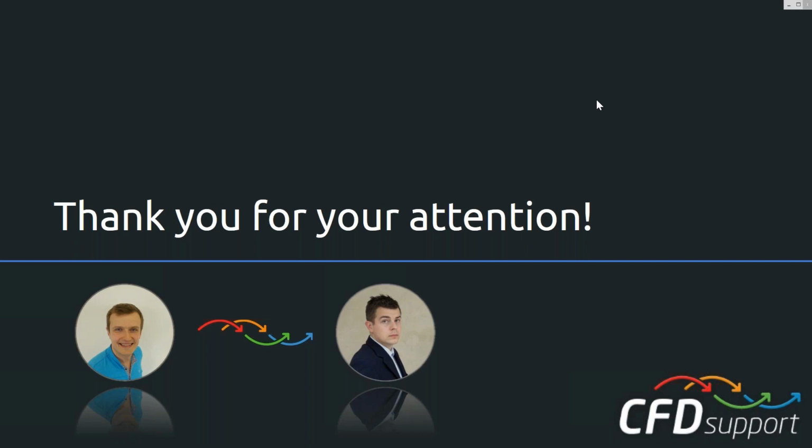Francisco is asking whether SnappyHexMesh is compatible with other software. Well, I think not very much, because it creates a lot of polyhedra, and as far as I know, a lot of commercial codes are not familiar with, for example, 52-face cells like SnappyHexMesh sometimes creates.